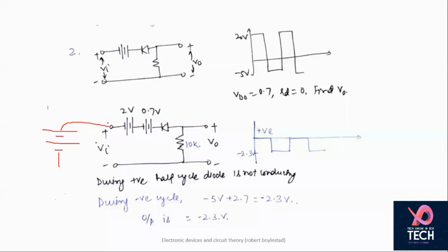It is acting as a series connection. Yeah, this is a series connection. So this is 20 volts. This is 2 volts corresponding to the battery given in the question. And this diode is not an ideal diode. This is a practical diode. So we have substituted here your constant voltage drop model. So we are putting here a 0.7 volts diode here, battery here, and this is your diode.